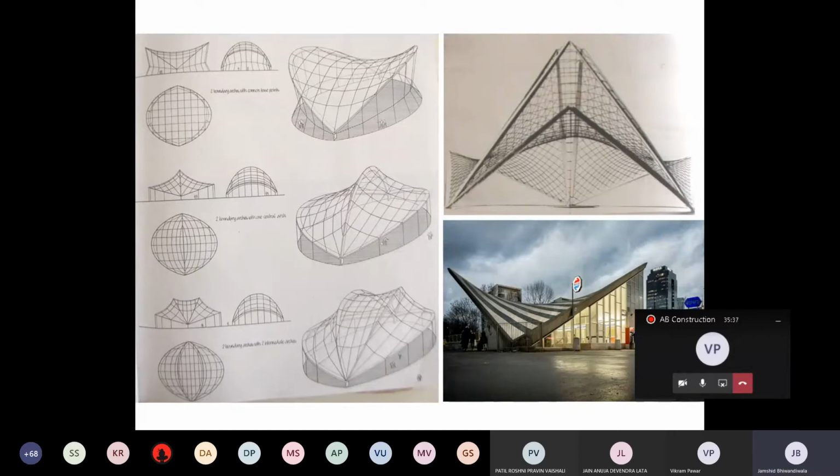You'd use the arched frame to be in a position to work with the tension of the cables. So here you do not only see the arched ring used as a pivot, but you also see the arched ring or the arched frame as an edge member. That's very important, and that is leading to the forms that we are seeing.